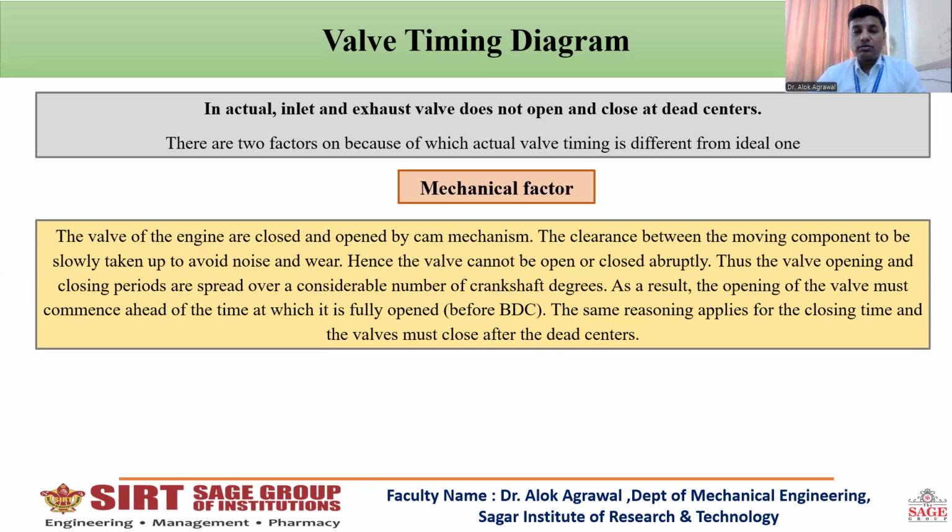But if we want our valve to open when the piston reaches top dead center or bottom dead center, we have to start the mechanism of opening before it. So because of this mechanical factor, we need to consider that the inlet valve or the exhaust valve opens and closes some time before, not at the dead center.